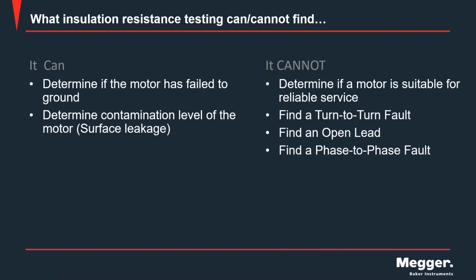It's also important to understand what it cannot do. It cannot determine if a motor is suitable for reliable service. It can't find turn-to-turn faults or opens or face-to-face faults in the way that it's performed with these testers.